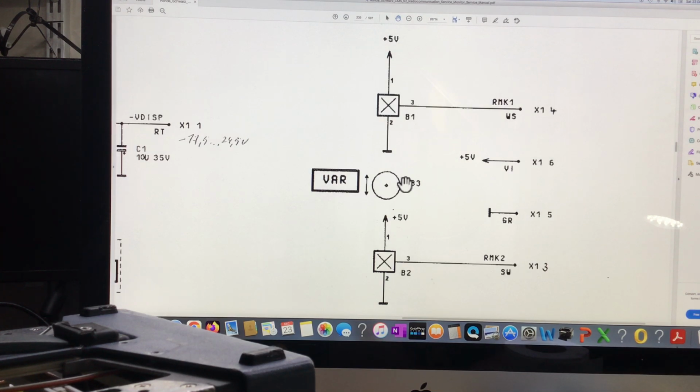So I definitely think there's some merit in this, where there's either some magnetic materials that have got stuck to these, contaminating these sensors, and it needs a clean probably, or some foreign debris got in, like iron filings or something like that, and it's picked up round these. Or it could be the sensors themselves, how they're positioned in the control, may have become detached from where they should be and are floating around in places where they shouldn't be, and thus picking up false signals from this magnetic disc, and thus creating this false symptom.